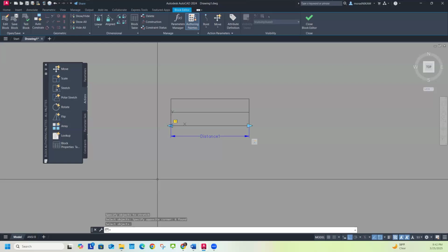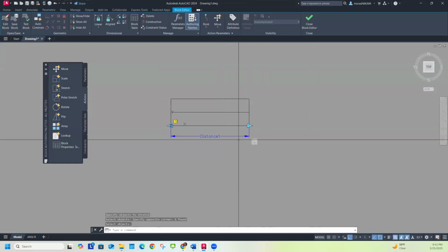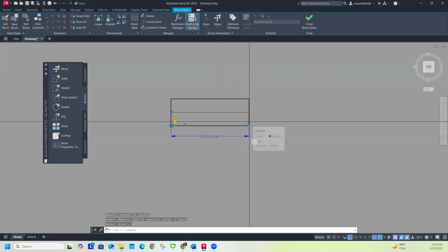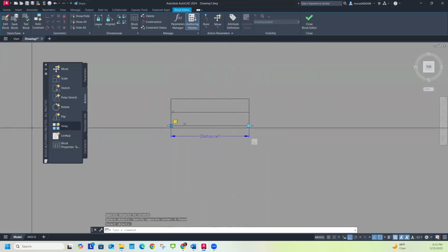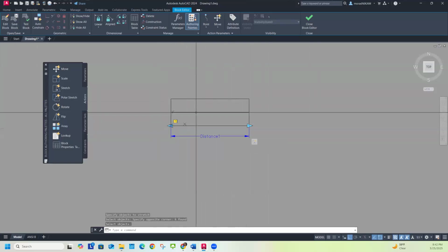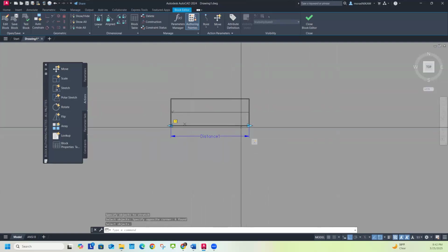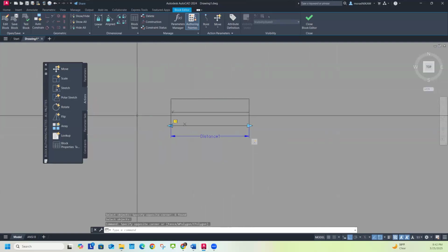Okay, and so now I selected all that, and now one of the yellow exclamation points is gone, which is on the side. This side still has one because this arrow doesn't have any parameter. It's not going to be stretching from this side. All right, and then I want to open up the properties palette so that way I can make sure this stretches by specific increments.